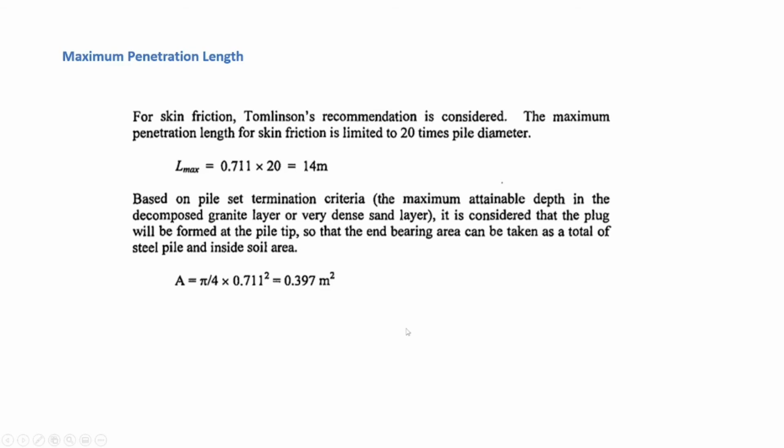Maximum penetration length. For skin friction, Tomlinson's recommendation is considered. The maximum penetration length for skin friction is limited to 20 times the pile diameter. Thus, L max equals 0.711 times 20, equal to 14 meters.